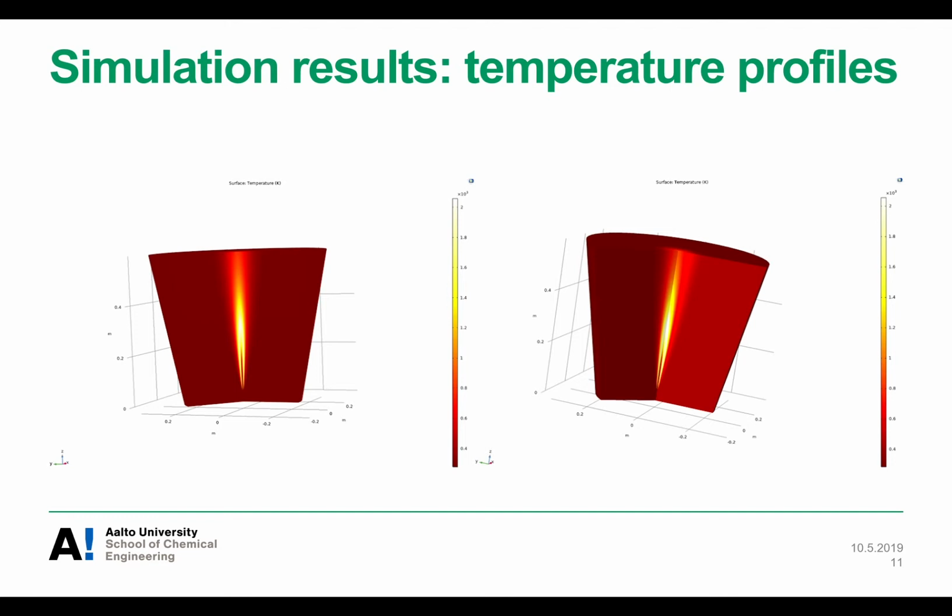Now this does make sense, because for each molecule of whatever feedstock, in this case we're using syngas, but for each molecule of carbon monoxide that is burned, the same amount of energy is released. It has a specific energy that it releases, and that specific energy translates to a specific temperature, right? So this explains why the temperature profiles are the same, because even if we had higher velocity, it would still be the same amount of energy being released per molecule that is being burned.